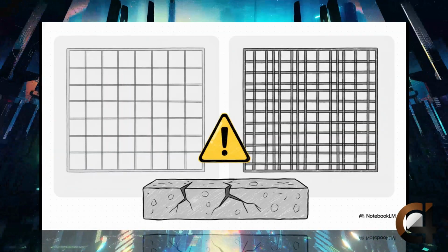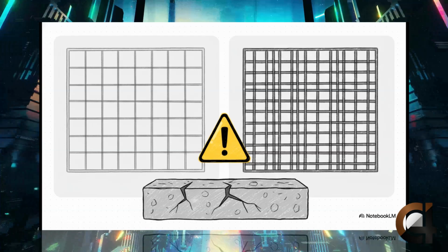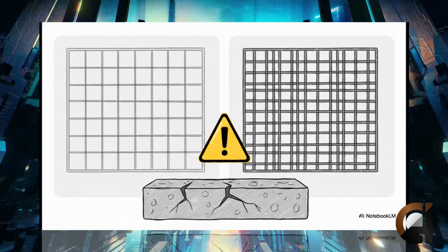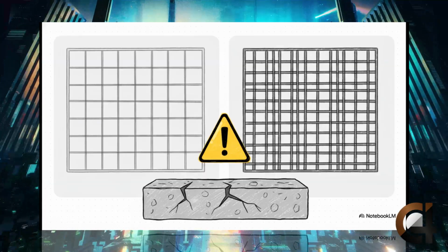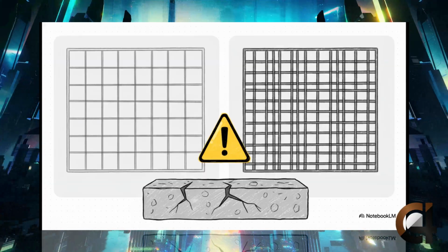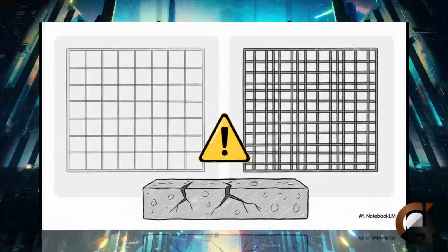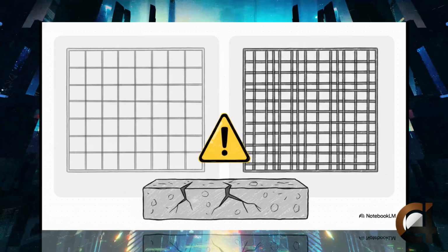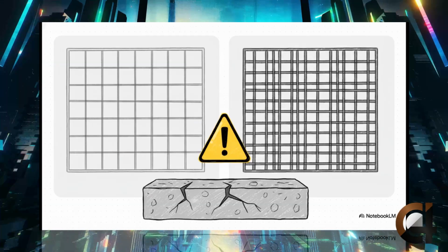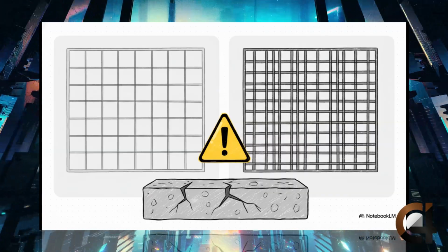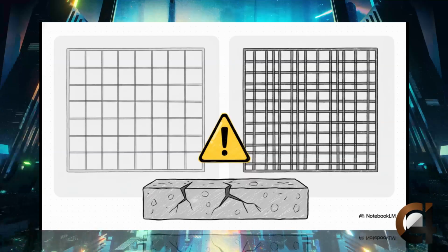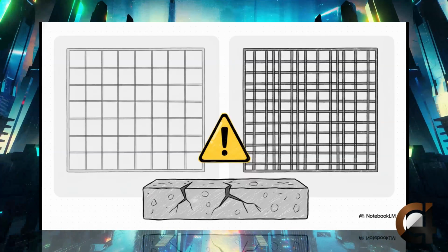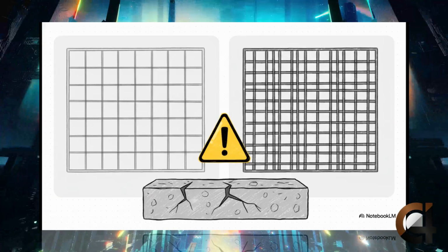So the crucial point is that it gets even more serious than just a quirky typo. Let's look at the mathematical data for the steel reinforcement bars, the rebar. Up in the top left plan view, it explicitly calls for 13 top bars and 13 bottom bars. But if you cross-reference that with the reinforcement details box in the bottom left for the exact same pad base, it lists 20 bottom bars and 18 top bars. Wow, that is a massive mathematical contradiction in the structural design.